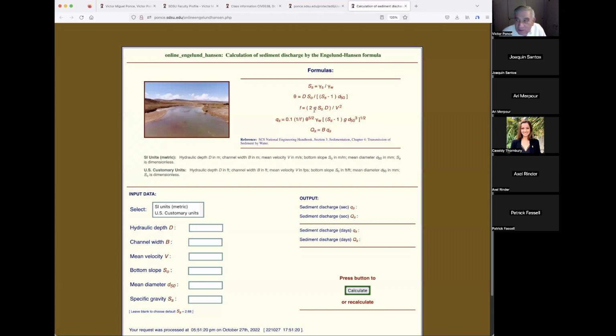Now, I have studied this extensively, and this issue of friction appears not just in civil engineering and hydraulics, it applies in fluid mechanics, it applies in chemistry, and so forth. Different fields utilize this equation in various forms. And I know for a fact that the Darcy-Weisbach is not the most popular. Some people use 4 in there instead of 8, and they call it something else. They call it a drag formula and so on. It's got all kinds of different names. The one that doesn't have anything, it has just a 1, that's, I already told you, the Ponce equation. I gave it the name because nobody's using that. Why is it that the simplest equation is not being used?